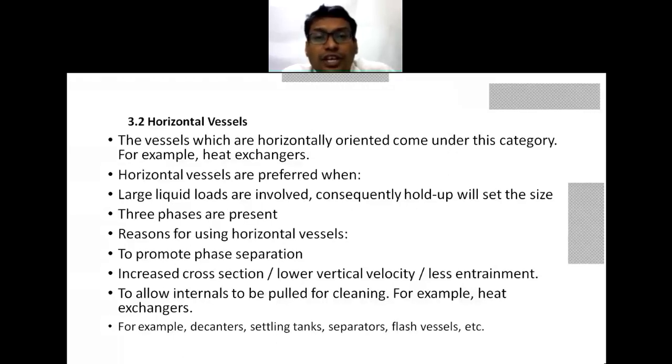Then when large liquid loads are involved, consequently the hold-up will set the size. When three phases are present, including a solid phase, these horizontal vessels are preferred.